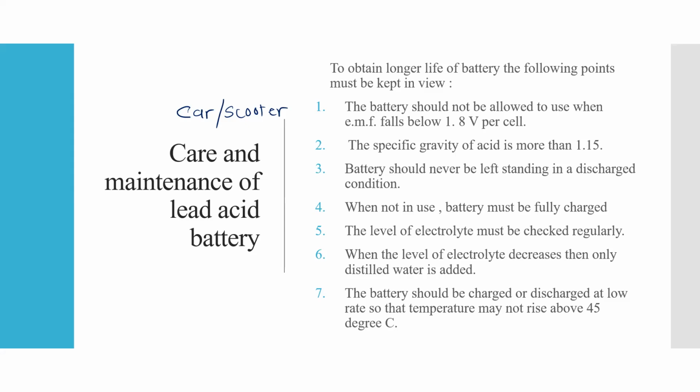Okay, the charging rate must be controlled very, very carefully in case of battery. Okay, you can't simply connect your battery to any amount of voltage, any amount of current. We should be very, very careful. Otherwise, there are chances of explosion in the battery, because batteries, especially the lithium ion battery in our mobile, is very sensitive to the level of charge. And because the chemical is involved, so we should not allow the temperature to rise above 45 degrees.